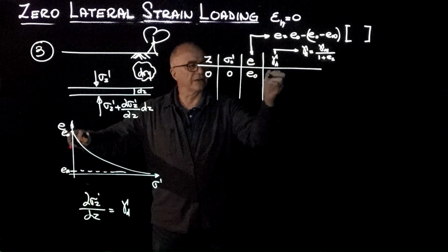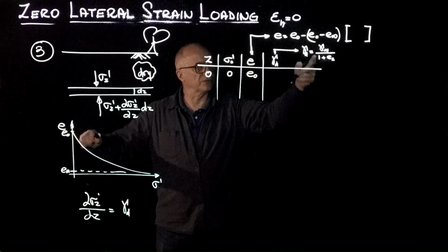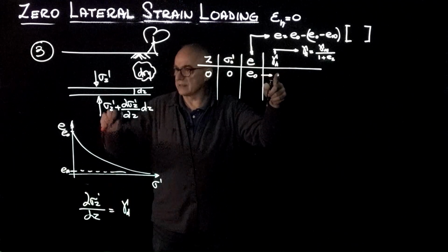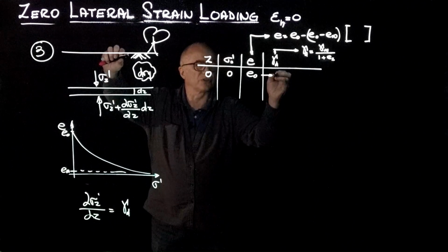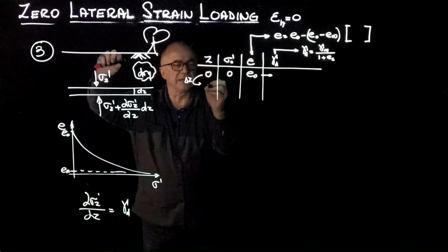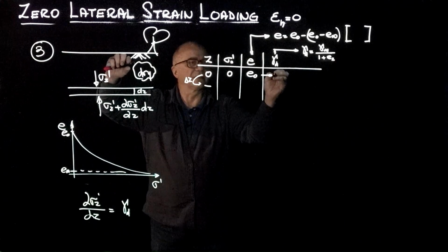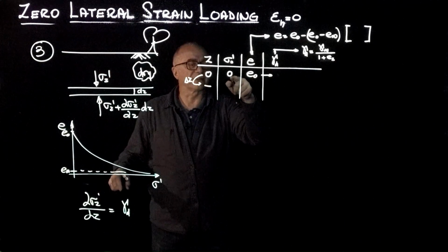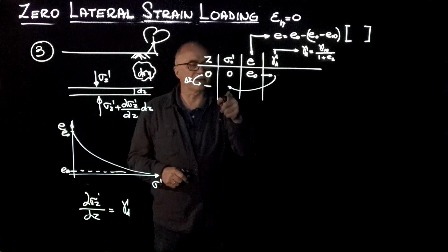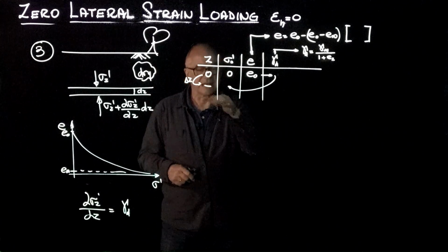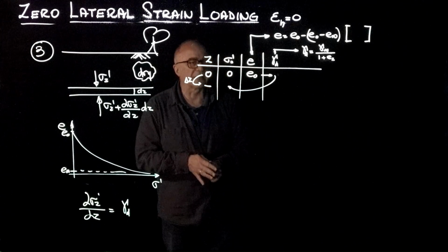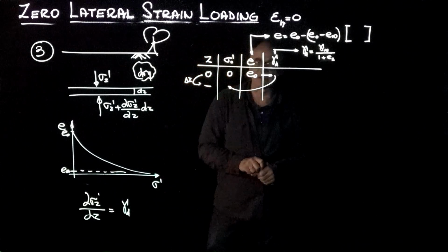And based on that, you can compute with the equation that relates void ratio to dry unit weight, the unit weight. Now, that unit weight is for the slice which is very much at the top, which is going to apply the load on the next one. So if we increase here by Δz, now you have a new value, and this unit weight adds to the effective stress above times dz. It will add to increase the stress, higher void ratio, higher density, etc., and you integrate to any depth desired. So we're going to effectively do it numerically, and yes, there are ways to improve the algorithm I have just described.